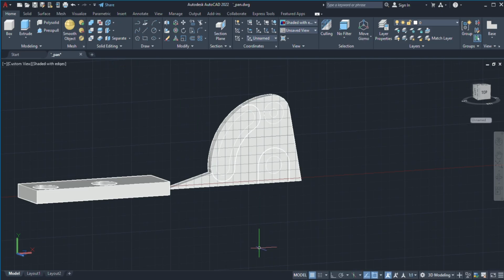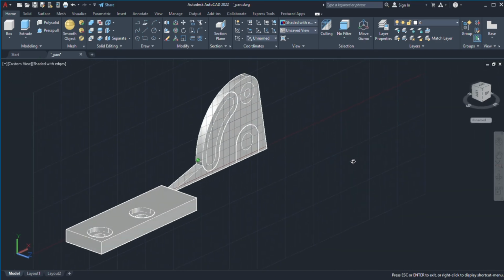Now we can press pull that by 35. Was it 35? So press pull that one by 35 outwards. Let's first orbit it a little bit. Press pull. Now if the press pull command isn't working, just move the image to another place.